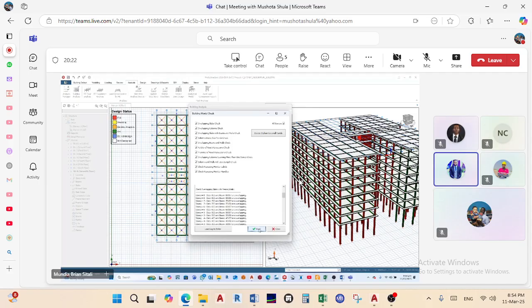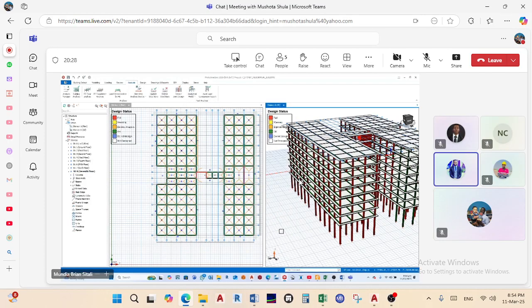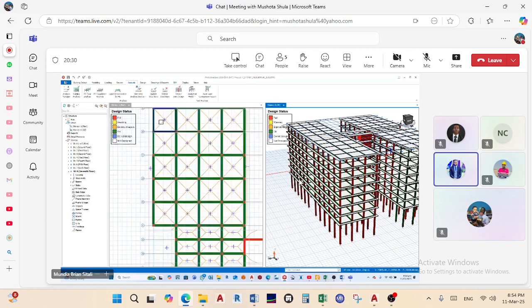So there's a way to sort out that, which we're going to do just now. So here I say close, and then I come back to story number 8. So an easier way of finding the beam, it's better to actually find the beam, then you see the localization of that error. So we open the beams tab, then we look for 8157.